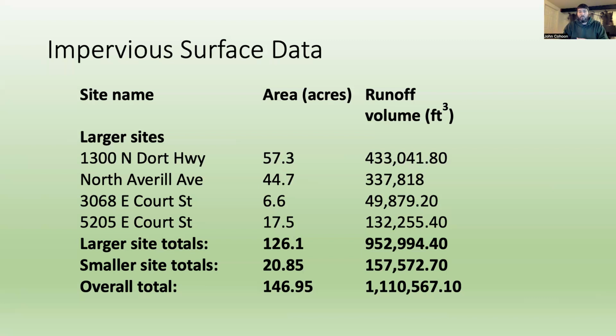lot better. And so essentially, every time we get a rain event and we're channeling all that water into the creek at once, we're just stirring up that creek, and we're pulling all of that sediment out of the banks, and we're washing it downstream. And so if we can reduce that as much as possible, we will be, as a watershed, in much better shape. And so, if we can de-pave, if we can add in some other types of green infrastructure, hopefully we can reduce some of that flashiness, and we can start to slow down a lot of the